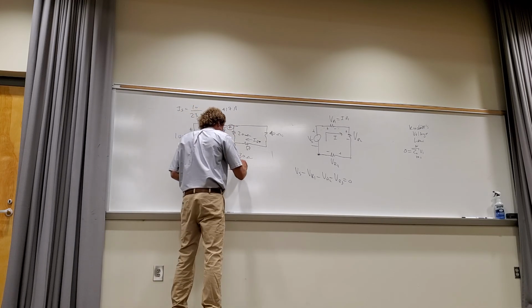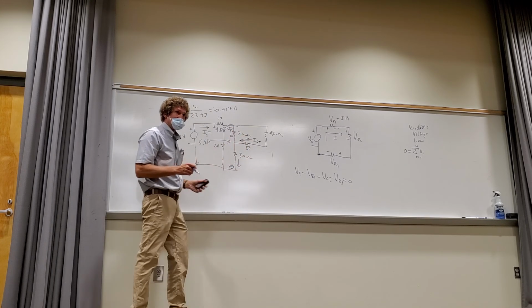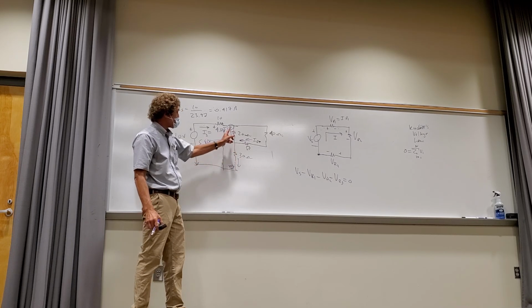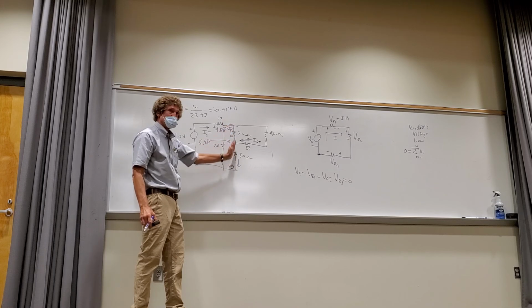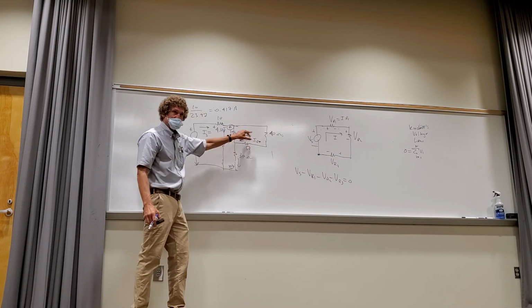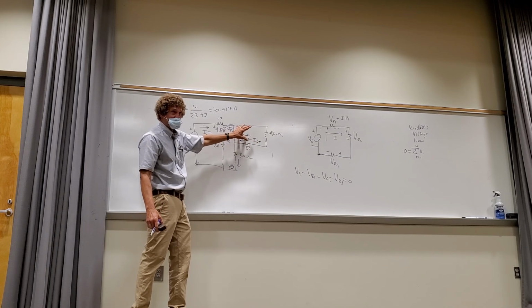Because if I get the current down here, I know that current's made up of this current and that current, right? But see, if I get the current flowing here, this is my way of reasoning. Y'all agree if I have the voltage here to here, and I want just the current flowing here on this outer part, I could sum these two together, put them in series, then in parallel for an equivalent resistance of 16 point whatever it is, right? 16.67 ohms.